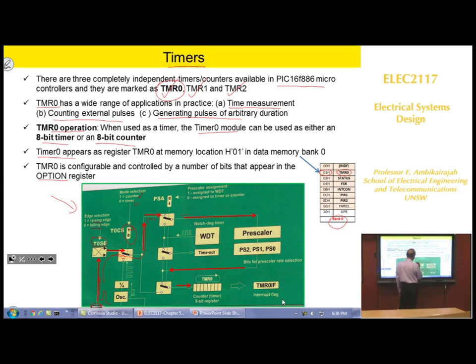And then the clock frequency can be changed, so you can actually divide the frequency. In counter mode, you may not need to divide, but you can still divide, and depending on how you want it, you can set up a value here, and I'll provide you a table there, and then you can divide the clock frequency.